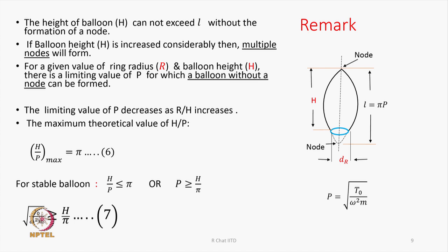So, you have to make sure that too much increase in balloon height under given circumstances may not be possible, but the challenge is how to make a big balloon, a lengthy balloon, so that we can have a long package, and the package is big, we will be able to wind more yarn. So, from the point of view of increasing the content of yarn in the package, we need to form a longer balloon. The package always resides within the balloon.